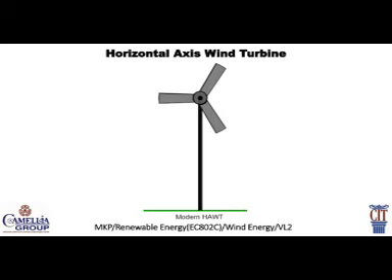The three-blade design is more mechanically stable and can have less torque ripple. The blade length may be from 20 meters to 80 meters and is usually bright white so that aircraft can view it comfortably. A turbine with blades of 80 meters may have a rating up to 8 megawatts.